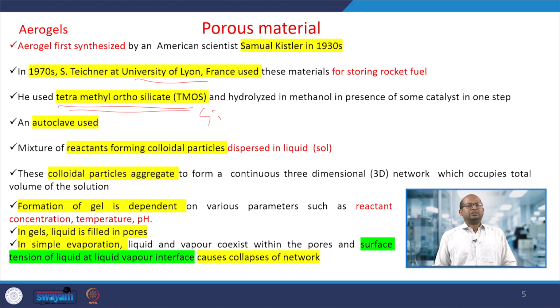Initially the precursor was taken in a solution, and then by gradual evaporation of the solvent it can be converted into a gel. That gel we can dry at different temperatures and by different procedures to prepare the aerogels. When gel formation occurs, 3D network structures are formed in the gel from the material we have taken, that is, tetraethyl orthosilicate. So the framework-like structure is formed.